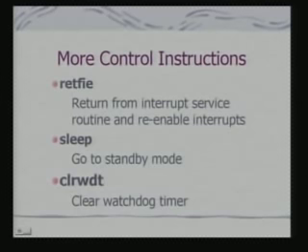Then there is the sleep mode of PIC, and this is a power saving mode. That means, when no useful operation is being done, the PIC processor should be put to sleep. So, there is a specific instruction by which the PIC processor can be put to standby mode.